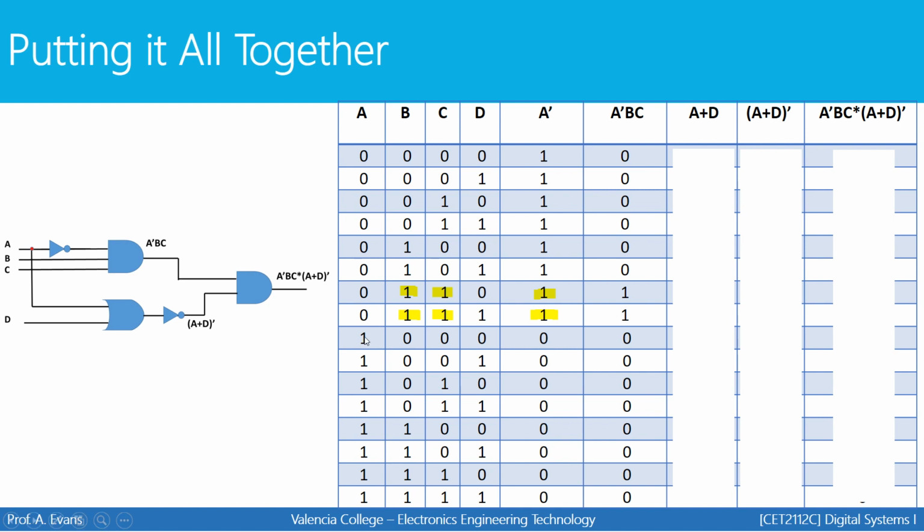And I can look down here and see this large group of 1s for input A. So I can look at this huge group of 1s and say, I don't really care what input D is. I know that because input A is high, I'm going to have a 1 for the second half of the table, guaranteed. All of these here are going to be 1 just based on A alone. For the first half, the top half of the table, A is always 0, so then I'm only going to have a 1 whenever D is 1, which would be in these 4 places here, here, here, here.